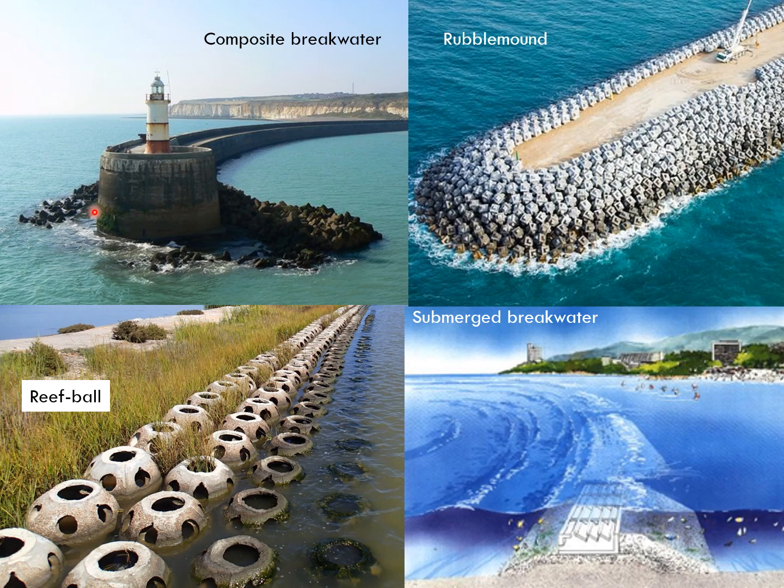maintenance work. This is the typical rubble mound type of breakwater with a crown layer which allows the passage of construction machinery, so that in the event that the rubble mound units are displaced, then access for maintenance works can be carried out much more easily.